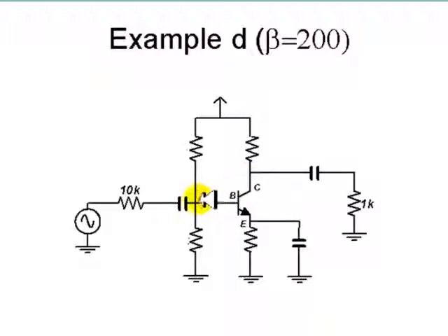That means the current in the base is positive and that the collector in an NPN transistor is higher than the base. How do we properly design a voltage divider common emitter bias circuit? Let's begin with the value of the voltage source. The power supply available, let's say, is given to us as 15 volts.